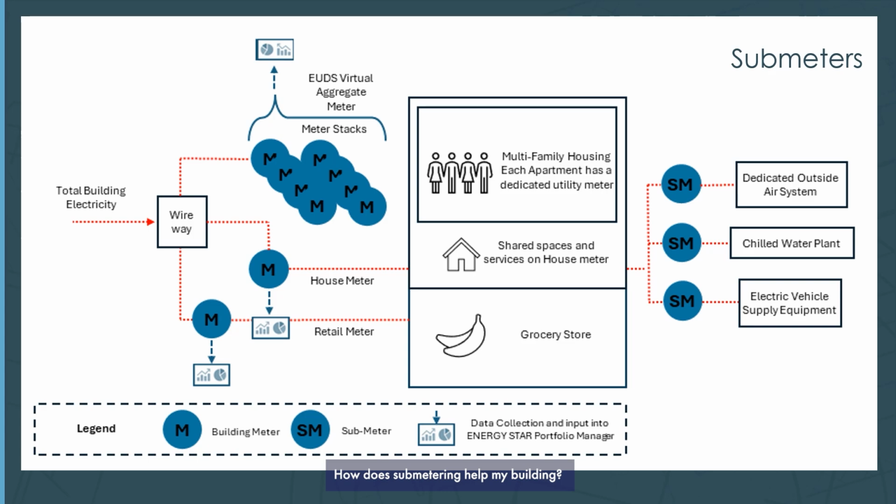How does submetering help my building? For energy management, submetering enables real-time and accurate usage monitoring, shows peak usage and any unusual trends, sheds light on energy-intensive areas, and helps make informed decisions on energy savings. After all, you can't manage what you don't measure.